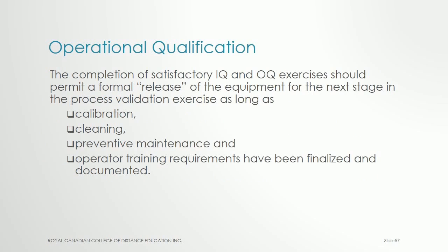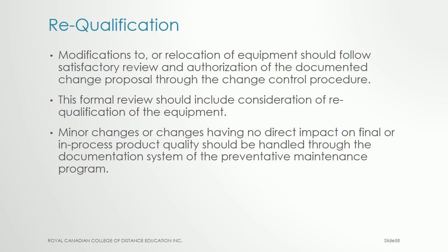The completion of satisfactory IQ and OQ exercises should permit a formal release of the equipment for the next stage in the process validation exercise, as long as calibration, cleaning, preventive maintenance and operator training requirements have been finalized and documented. Requalification. Modifications to or relocation of equipment should follow satisfactory review and authorization of the documented change proposal through